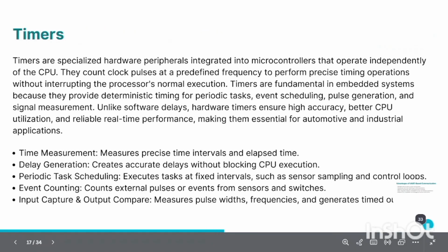Hardware timer independent execution. Hardware timers are specialized on-chip peripherals that count clock ticks at a prescaled frequency completely independent of the CPU. This independent operation allows us to measure precise execution steps and create deterministic event timings without using blocking software loops.